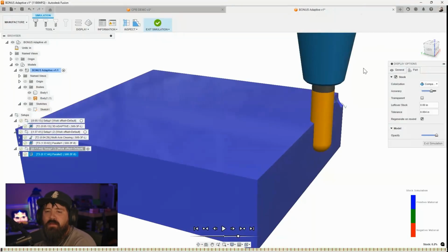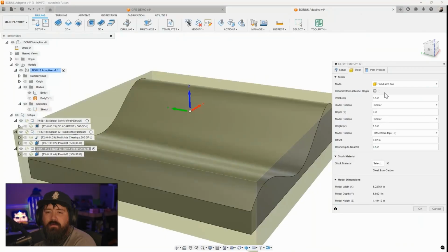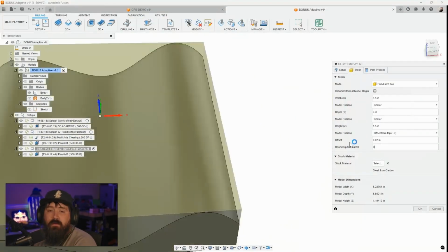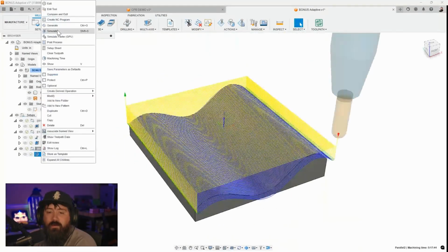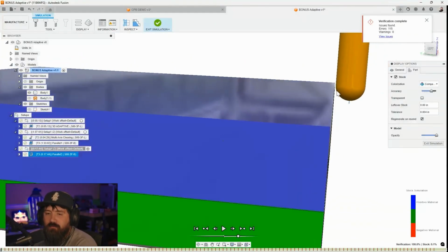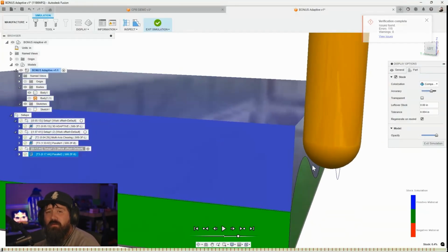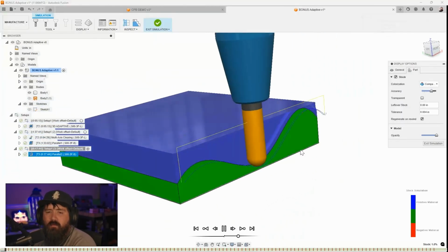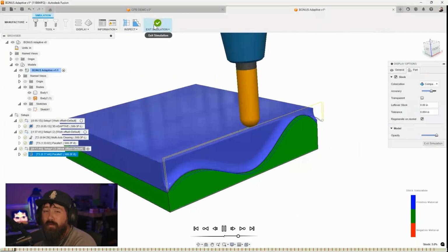You would want to go obviously the size of the material, the size of the part plus the stock that you have there. So we'll just make this to the nearest 0, and then that will give us what we want. So you would have added whatever that amount was, but this is why I had to do that, because our first pass will be cutting about nothing. So that value we could subtract a little bit of what we want our first pass to be, but as we go across here, we probably want to also extend it on the edges there to have it not plunge down into the piece. So pretty easy to do that.